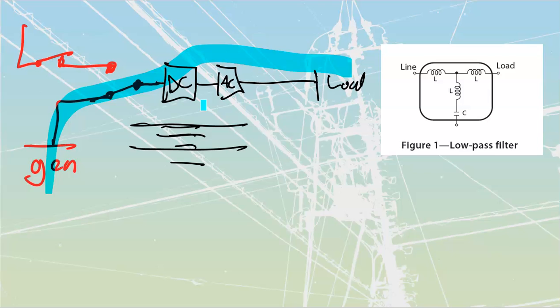Line voltage regulators are going to regulate the amount of voltage that we are going to have. Some of them can regulate the power, but they can't condition it. In other words, they don't smooth it, but they are going to be able to adjust the amount of voltage that we're going to have out, particularly ones like the tap-changing switching transformer or the variable ratio transformer. They are going to change the voltage, but they don't really filter a lot. We do have some others like our saturable reactor, our resonant transformer, etc., that will provide some power quality fixes as well inside of there.